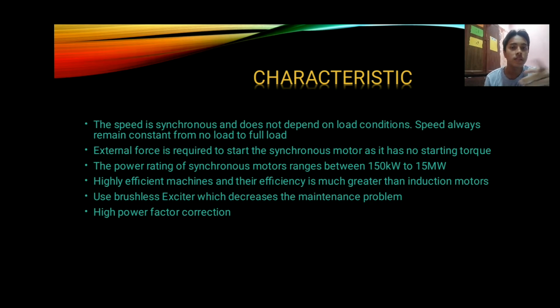Then next, an external force is required to start the synchronous motor as it has no starting torque. Then the power rating of a synchronous motor ranges between 150 kilowatts to 15 megawatts. It is a highly efficient machine, and its efficiency is much greater than the induction motor. It uses a brushless exciter, which decreases the maintenance problem, and it has high power factor correction.